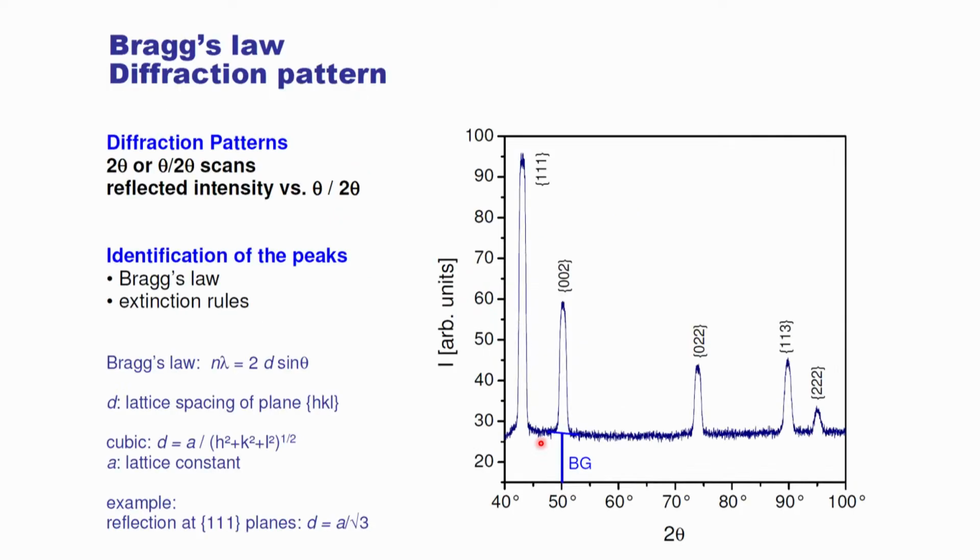Okay. Now for X-ray diffraction, this is just what we call an X-ray pattern, theta 2 theta scan. We're looking at the 2 theta position. So as we scan across the diffracting angles, that theta angle, and we scan across a powder or a nice polycrystal sample with random texture, we're going to see peaks every time that D-spacing matches our incident beam angle coming in, right? So as long as that 2 theta matches Bragg's law, we're going to get peaks of diffraction. When we don't, then we just get that background radiation, the Bremsstrahlung radiation, whatever we call it.